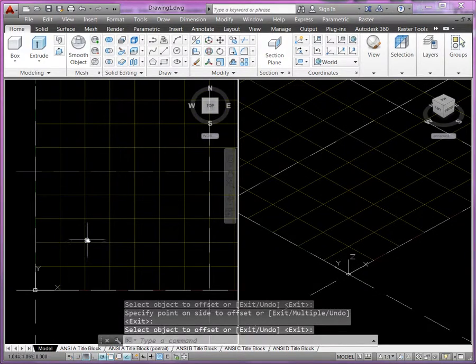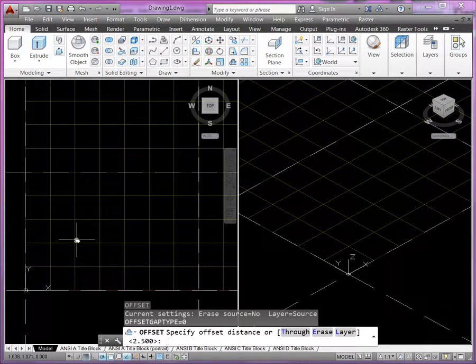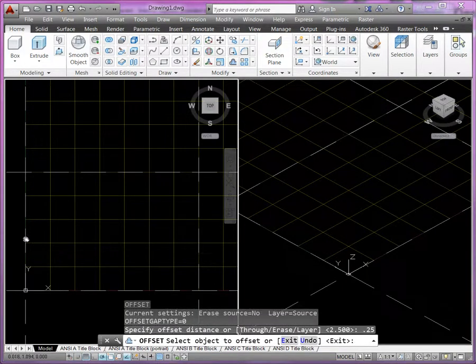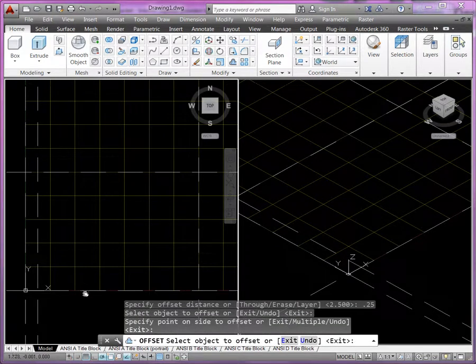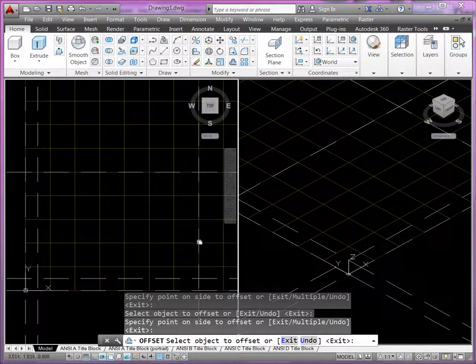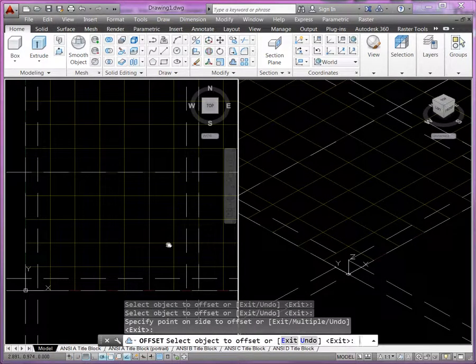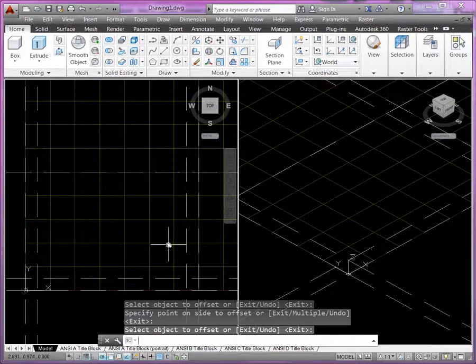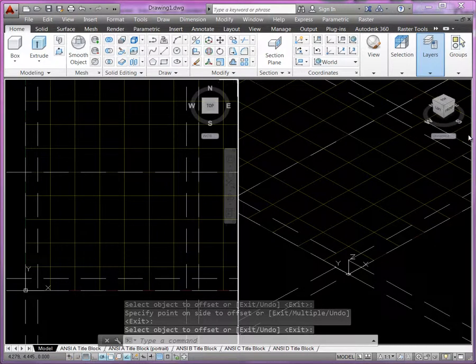And you can see this is where general shape and form will take place. If I offset now for the thickness, which is going to be 0.25, okay, I'm going to offset one of these construction lines here, the horizontal one right here, and the one on the right, and I'm making these offsets towards the inside. Okay. Now if I switch layers, I'm going to switch to the 3D layer here.